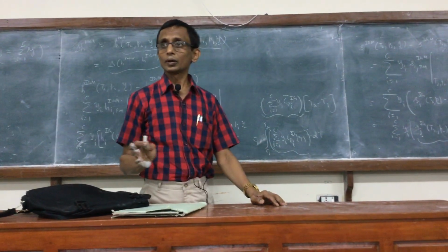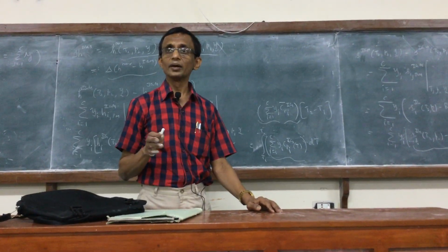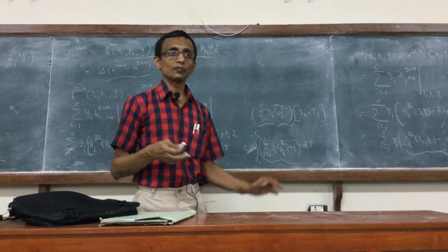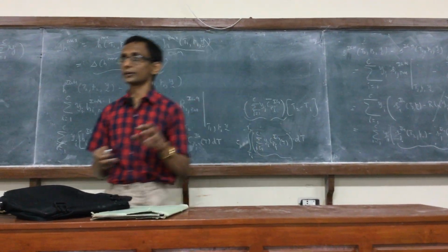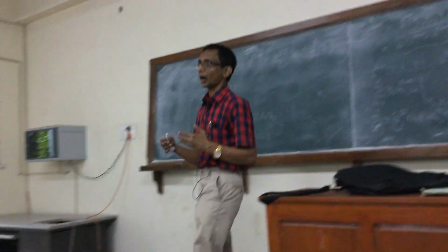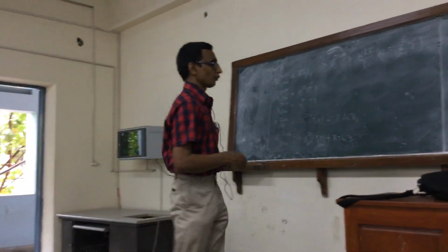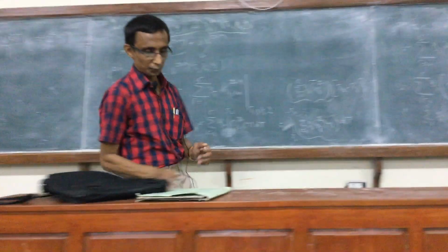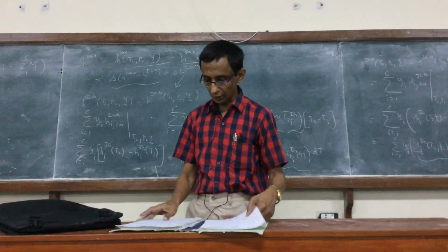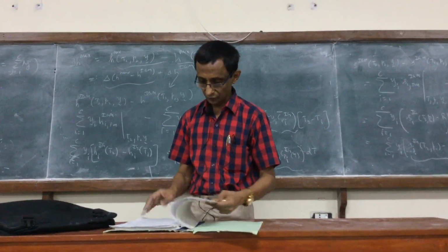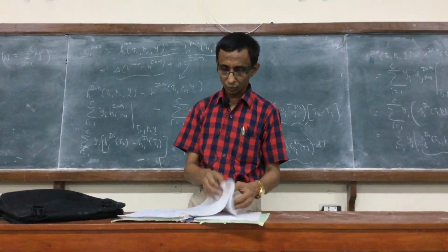You have to understand all this. Cp is what is given normally in the table. So if you want Cv for the ideal gas, subtract R from Cp, then you will get Cv. So you have to be aware of all this. So let's now take a numerical problem and see how to apply these ideas.